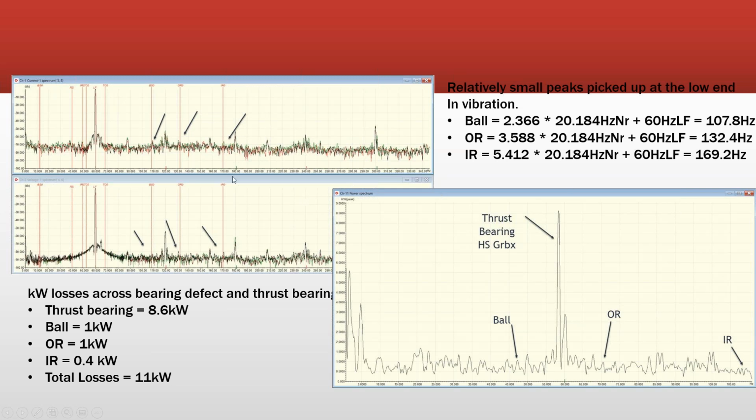This happens because in a wind turbine, I have the turning frequency, and then as part of my correction, using the drive or using up-tower control in a wound rotor machine, I create a counter-rotating field in the rotor as well, so that the field between the stator and the rotor is turning at something close to the number of poles of the machine times the frequency I'm interested in.